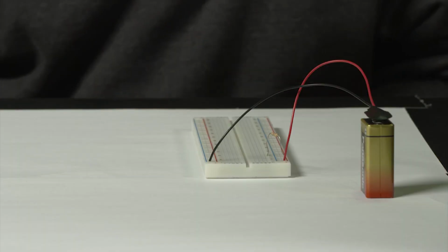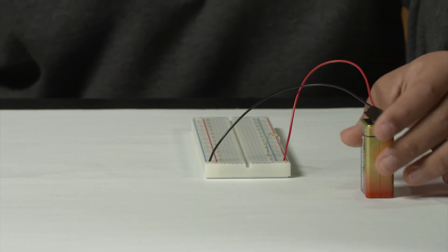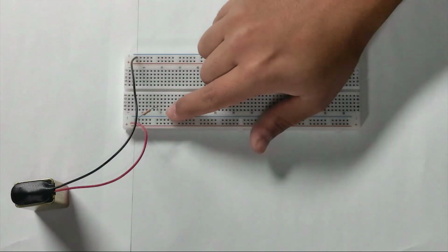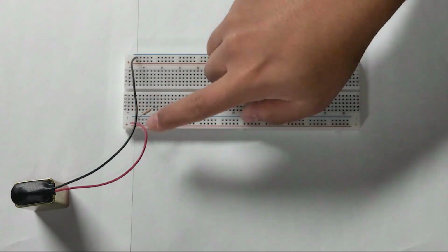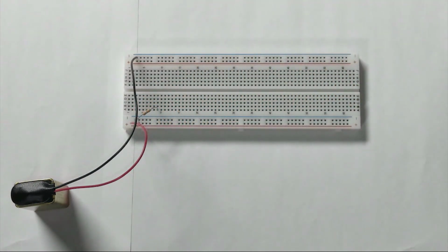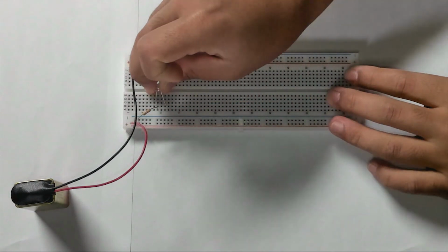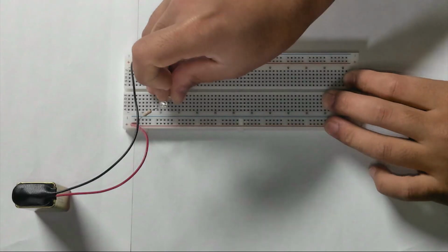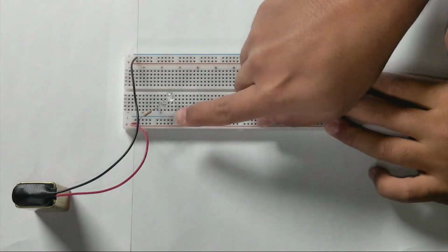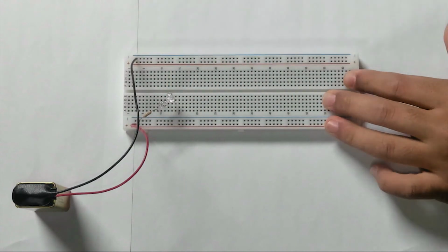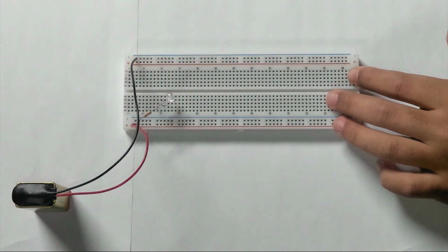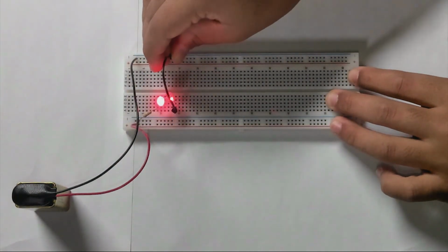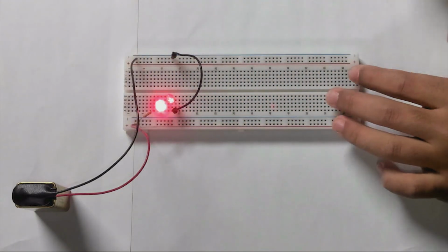Let's get started. Okay, so in this activity, again, the first thing we want to do is connect our battery to our breadboard. And then we want to add this 470 ohm resistor in series with the battery. Now the first thing we're going to do is connect our LEDs in series with the resistor. And again, in series means the negative end of one LED is connected to the positive end of another. And now we're going to complete this circuit by connecting the negative end of these LEDs to the negative end of the battery. And as we see, these 2 LEDs turn on.